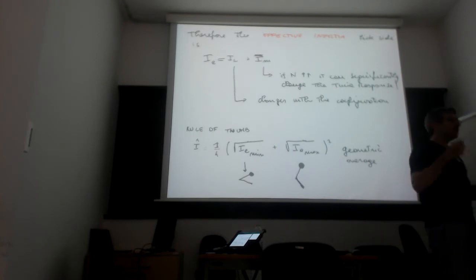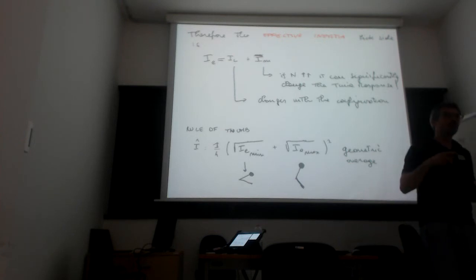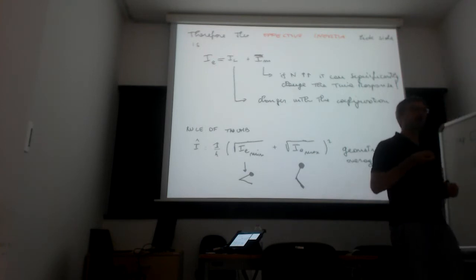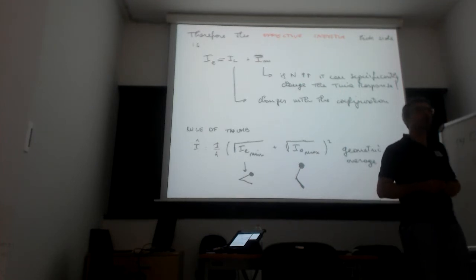So impulsively you can extract a very high power by overvoltaging, or you can liquid cool the coil and reduce the temperature by extracting the heat. This way you can have a small motor giving high current, high torque to the link, and also high speed.